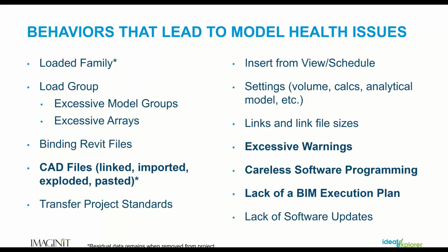I think in a week we had 5 to 10 calls, at least once a day, of somebody's Revit crashing because they had some software program or app they downloaded for free, and it was causing havoc. Once we got that uninstalled, the project was working good. So you want to be careful on some of these apps that you're bringing in. You want to vet them out to make sure they're not corrupting or doing things to your Revit model.